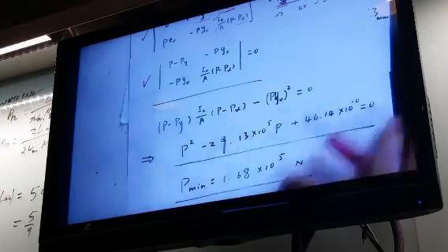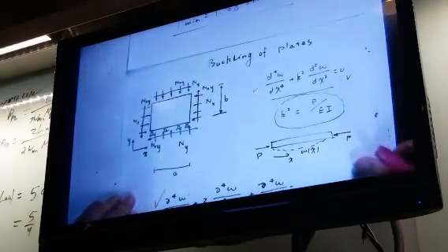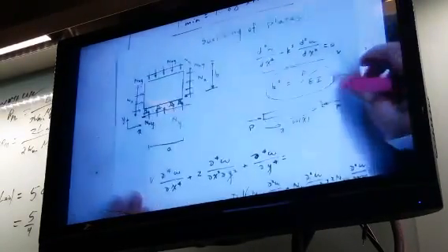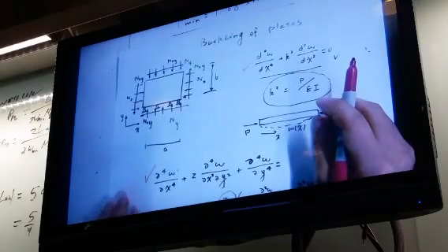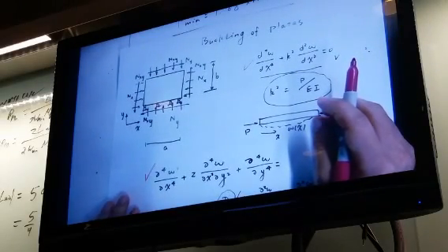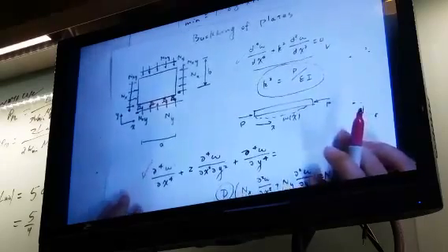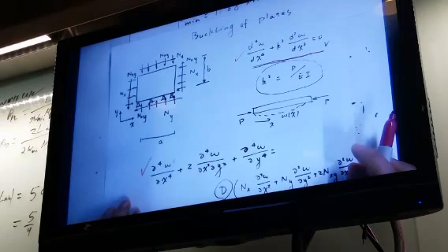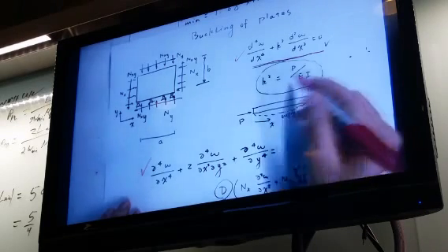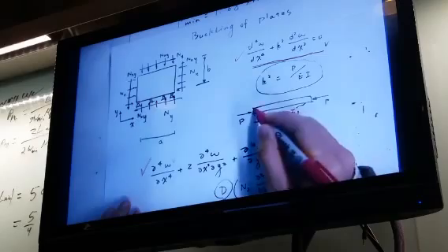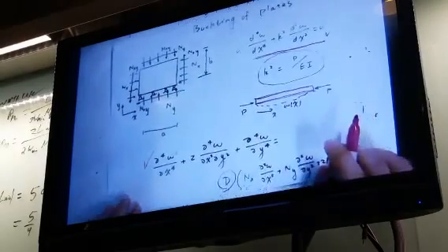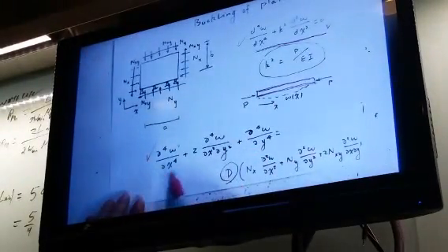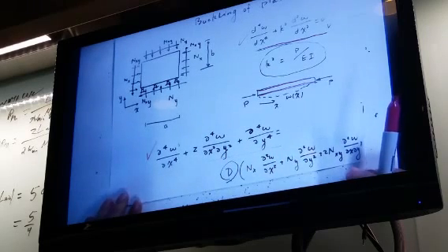The third thing we learned is the buckling of plates. So buckling of plates, we didn't go very deep because we did this problem using ANSYS. We didn't do hand calculation. But I introduced the governing equation. This is the governing equation for the buckling of columns. Right? K is related with the critical loading of P. This is one column structure. And parallel to that equation, this is the governing equation for buckling of plates.